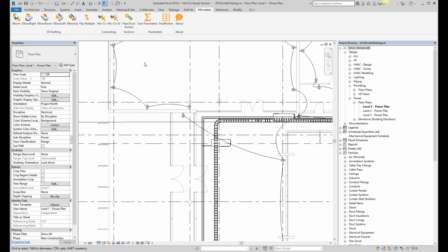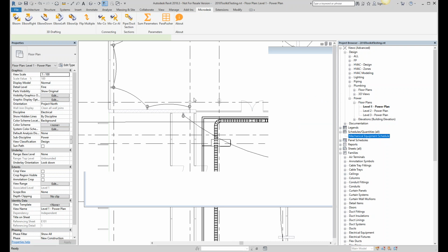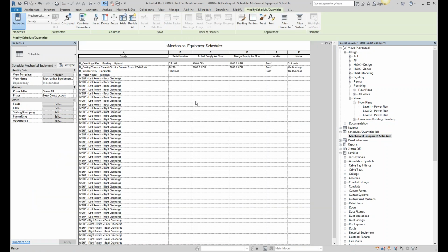So the Para-Pusher is along that theme, but it's solving a slightly more complex problem. And the problem we want to solve is adding parameters to families. I'm sure lots of people here have encountered this problem, but I'll summarize the situation. If we have a family that is part of our library while we're developing our standards, or perhaps it's downloaded as content from a vendor, often we need these families to contain certain shared parameters so they play nicely with things like our schedules and our tags.